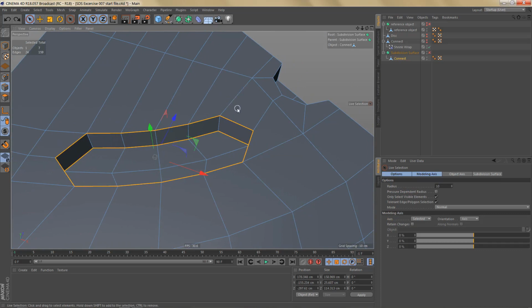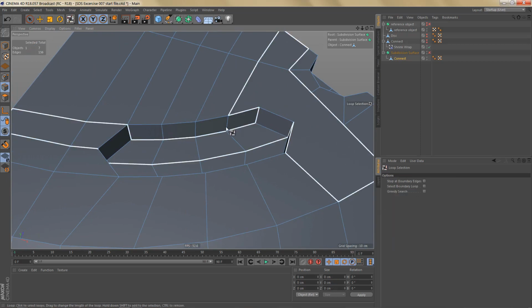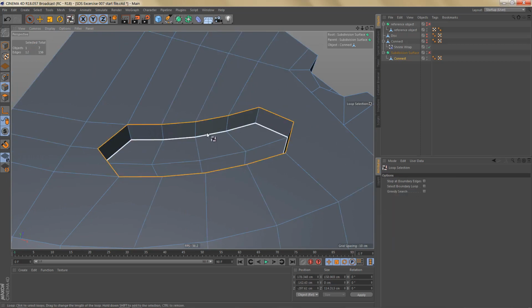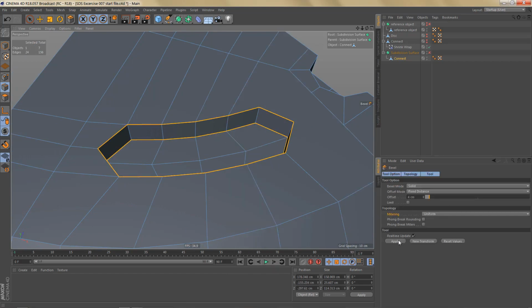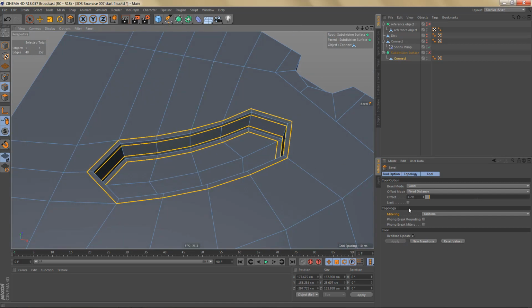And we can avoid this problem, which I think is caused by the fact that the bevel tool is trying to slide the points along the edges proportionally, and we can avoid this problem by turning this area here into an n-gon. And now if I loop select these edges here and these ones down here and apply a bevel, we are now getting even edges around that hole.